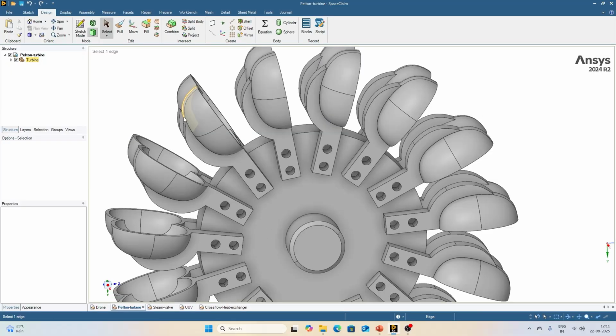Using the control option for multiple selections, please remember that you need to keep holding the control key until all the objects or entities are selected. If you release the control key, then all the other earlier selections will be cleared or unselected when you click the next object.